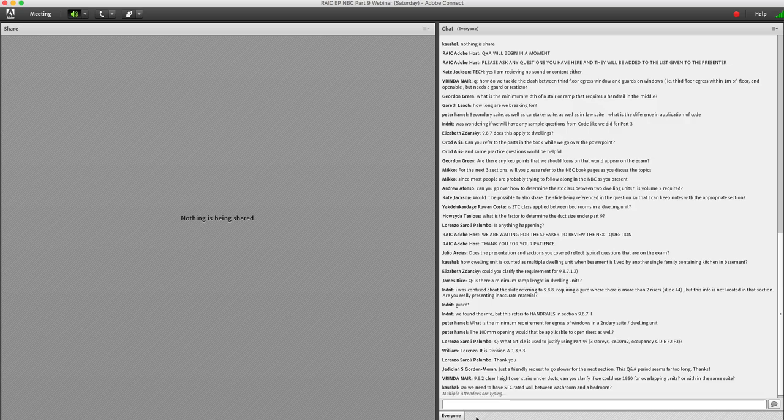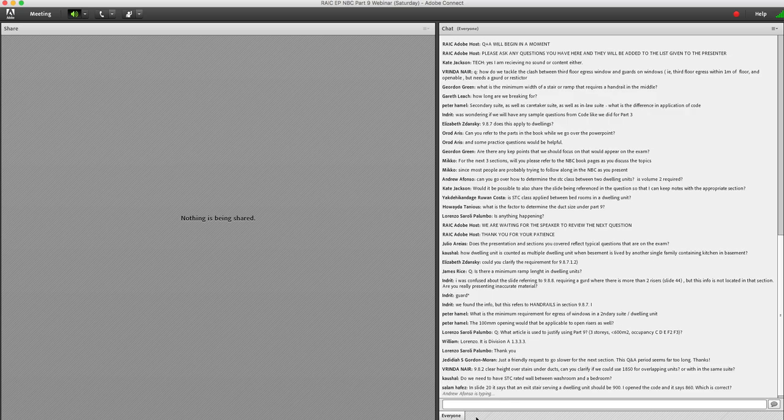Previous sections in 9.32 give you required minimum or maximum outdoor airflows, minimum airflows to specific rooms, and minimum exhaust capacities. So I believe this is what you're getting at: ducts for those applications.